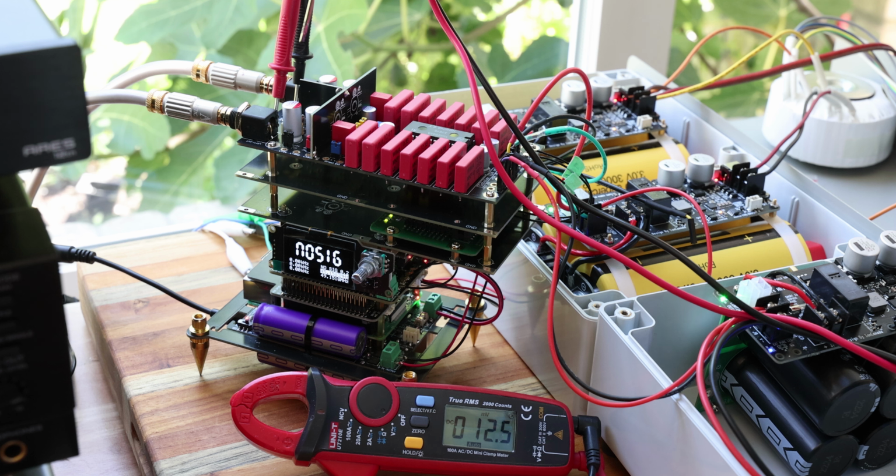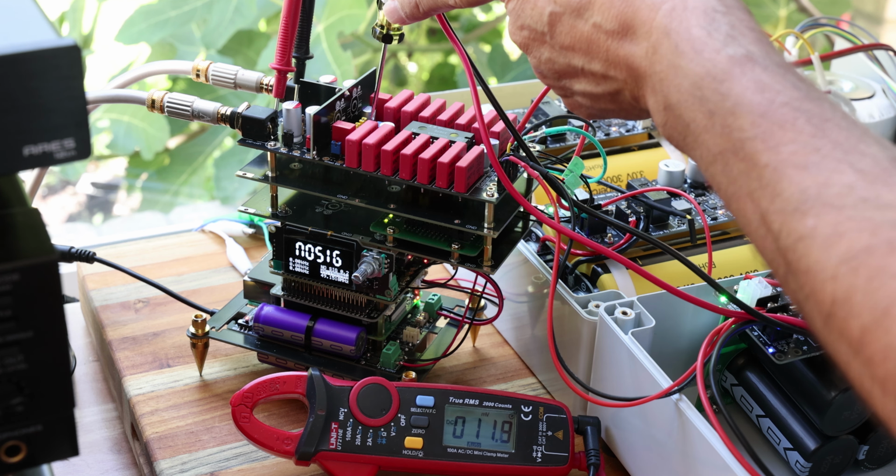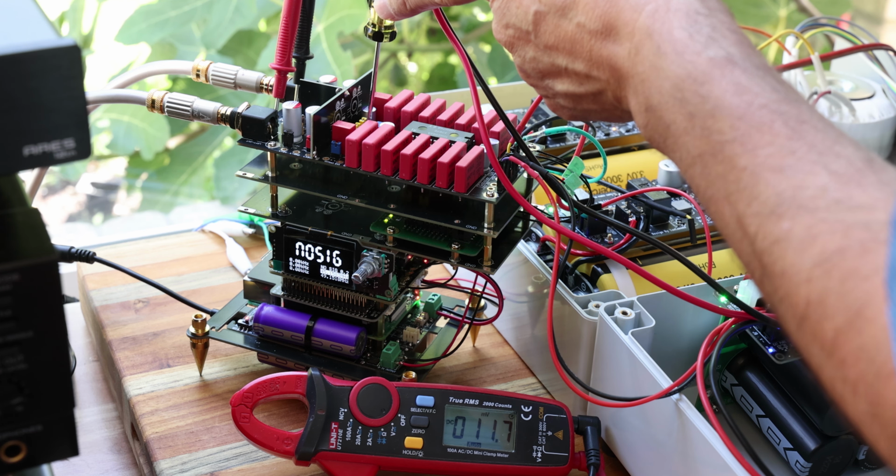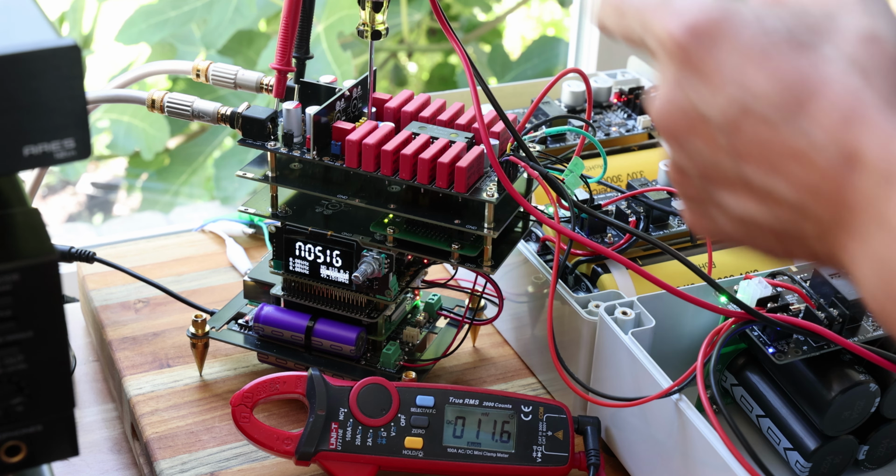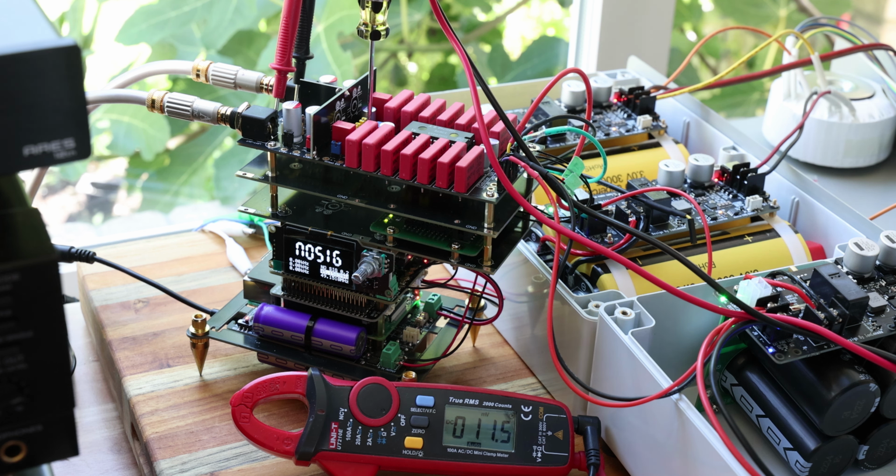Because the positive is on this side, we're going to trim this side first. Small amounts like this I wouldn't worry about, but I'm just showing you how to adjust it. It can go anywhere between plus and minus 2 volts, just to bear in mind. So right now we are at 11 millivolts. That's basically nothing, but we're still going to move it down. Here we go. And that's close enough, 0.2 millivolts, that's basically nothing.